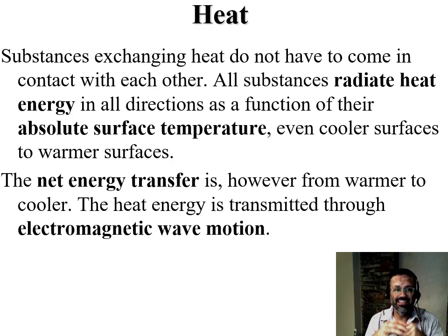But understand that everything is radiating heat unless it is at minus 273 degrees Celsius, or in Kelvin it is 0, right? So at 0 Kelvin you don't have any heat energy transmitted by electromagnetic wave motion, and that's how that heat is transferred, unless it is 0 degrees Kelvin. At that point, there's no vibrations happening, so you're not getting any of this radiant heat being transferred.